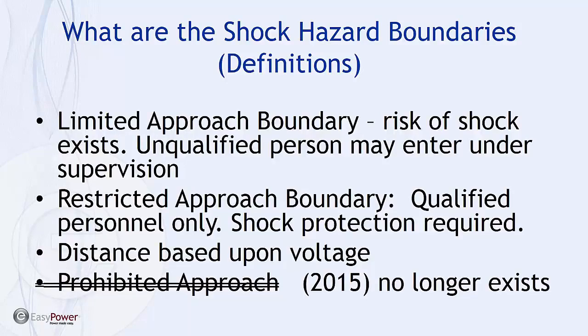Shock protection is required. And the distance in each of these cases will vary based upon the voltage at the exposed conductor. In the past, there was a third boundary referred to as prohibited approach, and as of 2015, that boundary no longer exists.